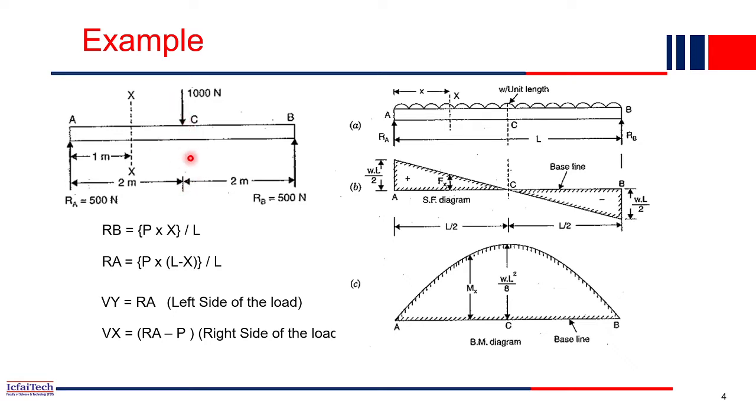Okay, so let's consider the same beam. Here I have tried to solve two beams. One is this one, a simply supported beam with a concentrated load or point load at the center, and in the second case we have considered a uniformly distributed load. So let's see the first case. When the concentrated load is acting, first we computed the reactions RA and RB. The vertical reactions are easy to compute as the structure is very symmetric, so there is no need to even write the equilibrium equation.